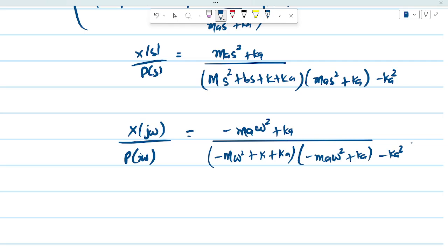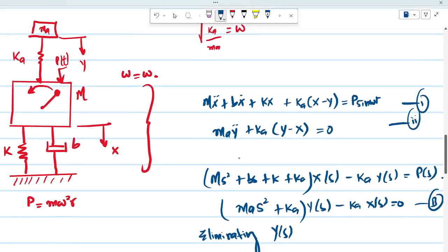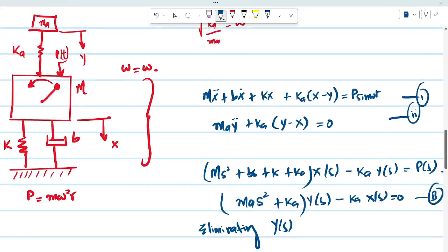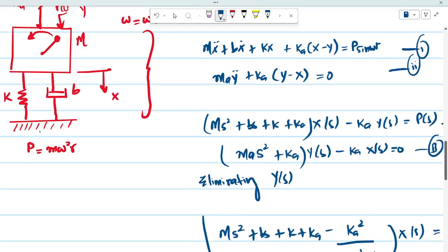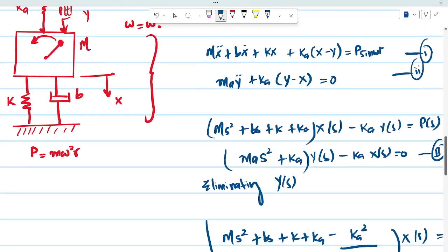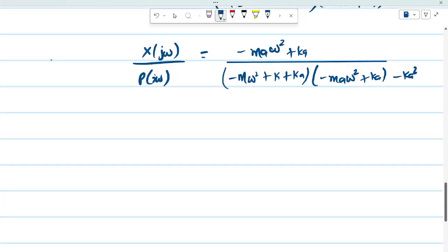In the actual system, the free vibration will eventually vanish because of the damping, even though it is small. And the force at the steady state can be represented by the equation now. As we have seen in the transmission of the force, if this force is acting onto the system, it is being resisted by this mass spring damper system, so the force transmitted is equal to the force resisting the applied force.